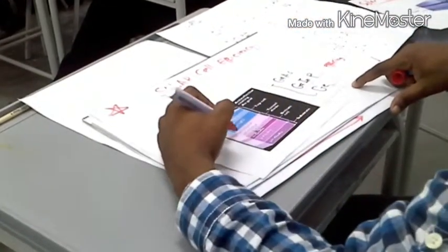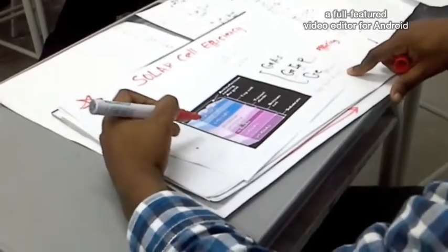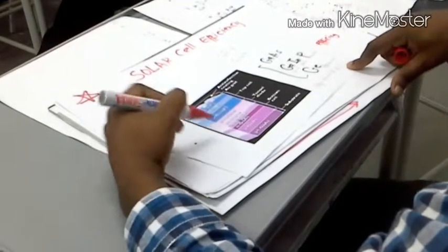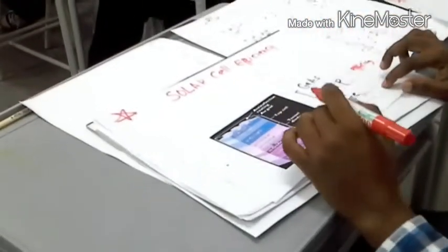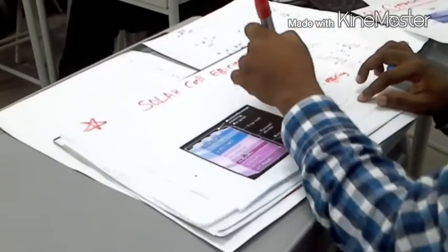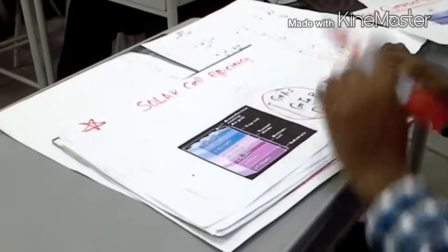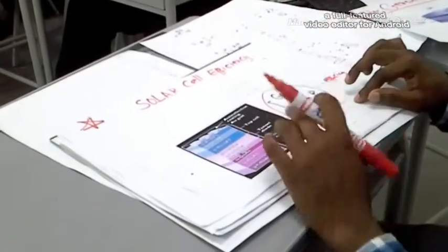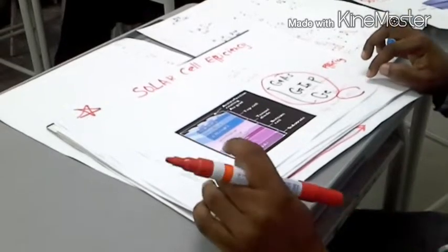If we see here, there is a multi-junction. The main idea of this multi-junction is to increase the efficiency of the solar cell. Up to date, the best multi-junction that can give us a high efficiency is the one composed of gallium arsenide, gallium indium phosphide and germanium. If we combine these three junctions, we make a multi-junction solar cell. With these three junctions, we can reach a high efficiency of 44%.